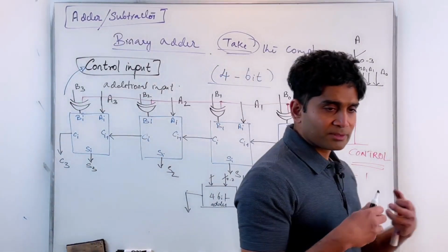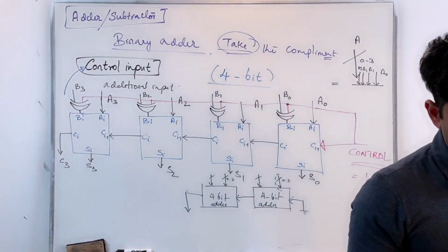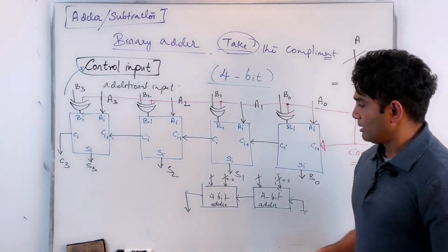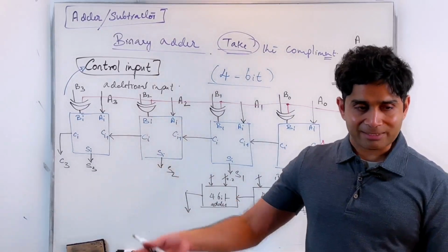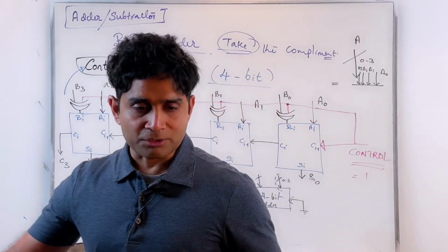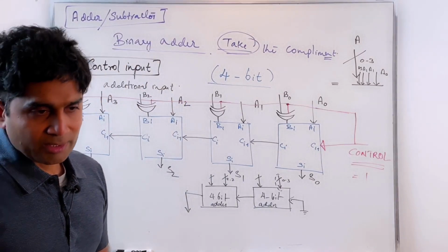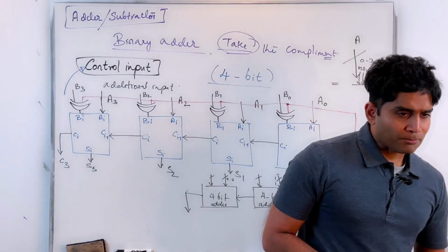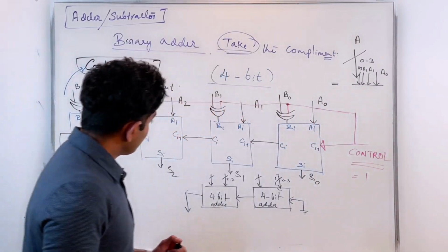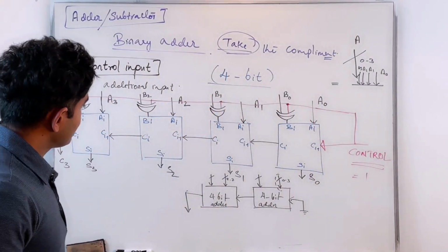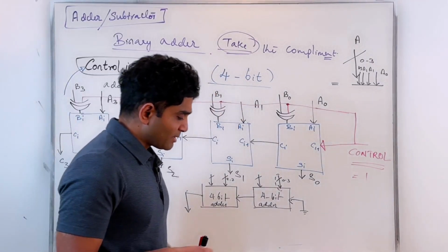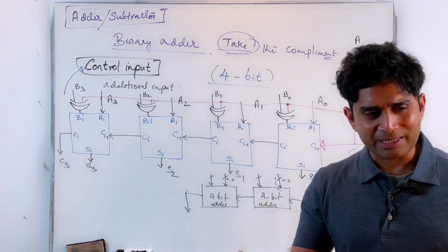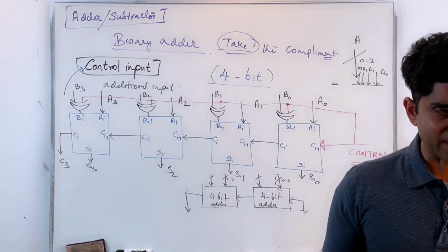So that's how I would make, using 2 4-bit adders, an 8-bit adder. Likewise, I can just keep cascading them together, and I can make larger and larger adders with this approach. All right. Now, I can do that, which is fine. There's nothing wrong in that. But I cannot just keep doing that, because eventually I land in a problem.